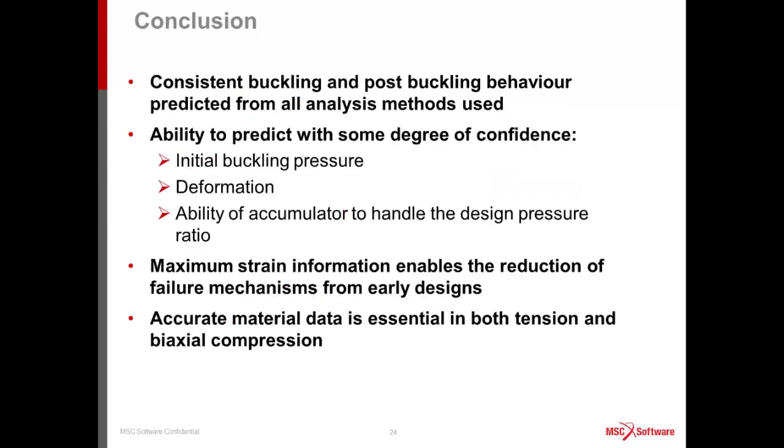So in conclusion, it gives us consistent buckling and post-buckling behavior. It's predicted from all the analysis methods that we used. It gives us the ability to predict with a high degree of confidence the initial buckling pressure, the subsequent deformation we're going to see, and it allows us then to design an accumulator that can handle a much higher compression ratio or design pressure ratio.